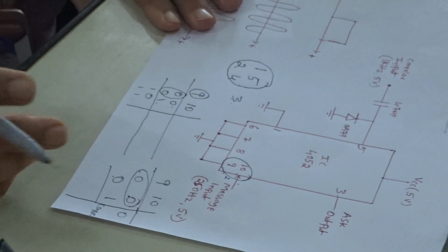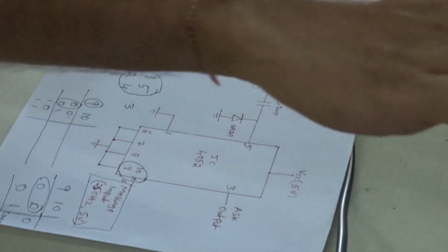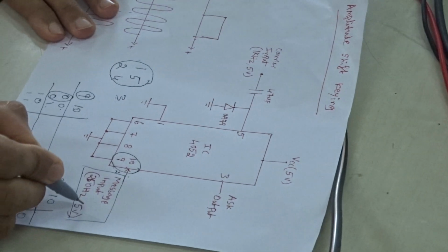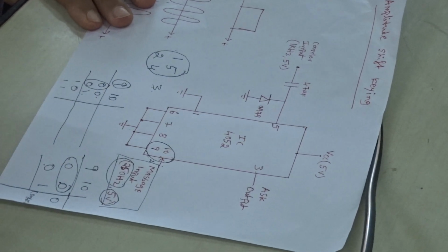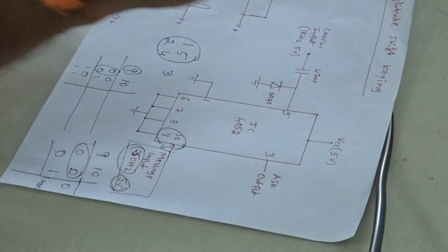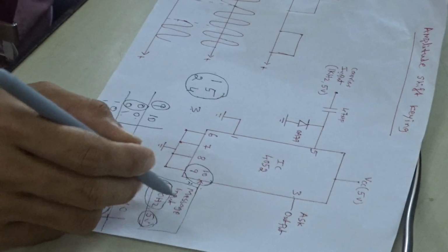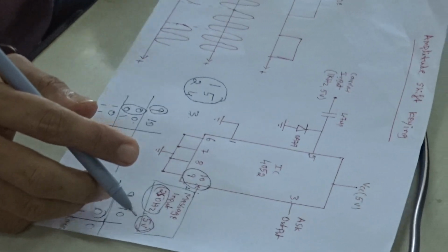So this is the simple circuit here. The message input is taken from a signal generator, and we have to set a square wave with amplitude 5 volt and frequency 250 Hz. When applying this square wave, we have to see that DC offset is applied, so we can say this message input is the input signal with DC offset.